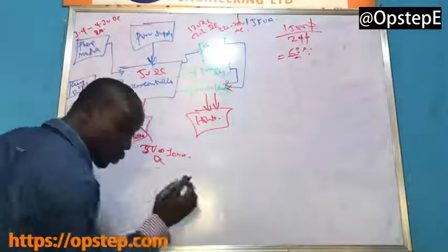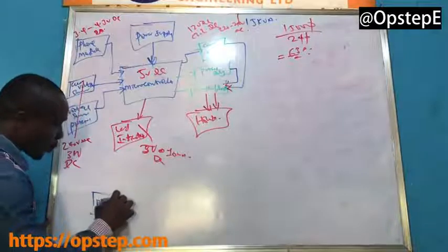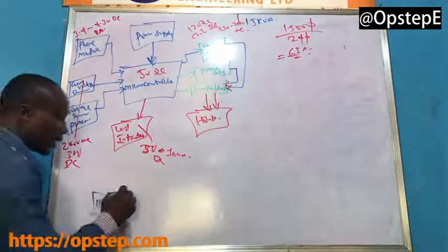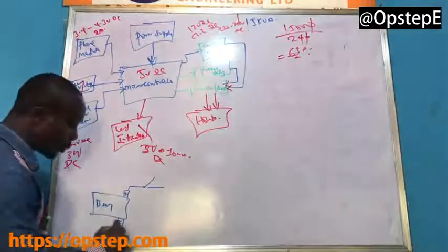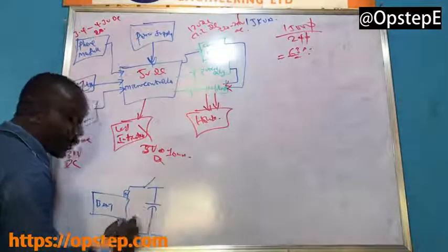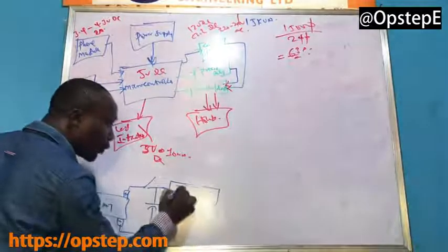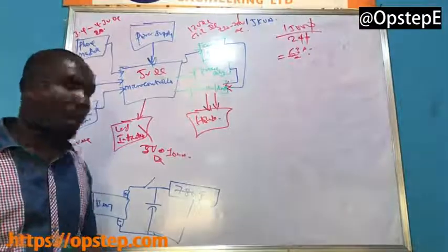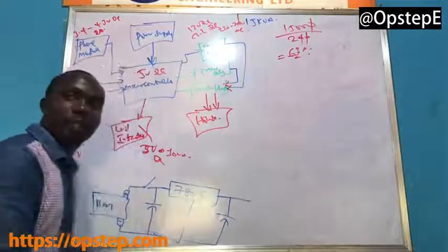Please look up, this is very key. You expect that you have a battery. Your battery is going to have a positive terminal and a negative terminal. The battery voltage is going to go through a switch. After that switch, there's a filtering capacitor before this voltage goes into a voltage regulator, a fixed voltage regulator, the 7805. The output of the voltage regulator is then filtered again.